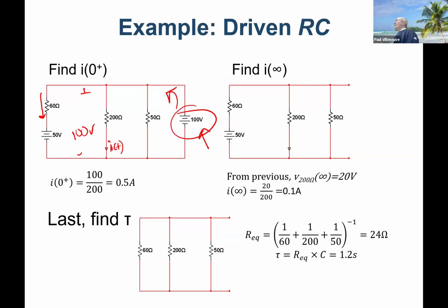So for a very brief instant in time, I'm actually dumping electrons into that 50-volt source. But that's okay, because the capacitor's job in life, right, is to store electrons or then send them back. So yes, I am taking it into account, but it doesn't matter because the voltage across it is higher. So that ideal voltage source acts like a battery at that point. It's taking power in.